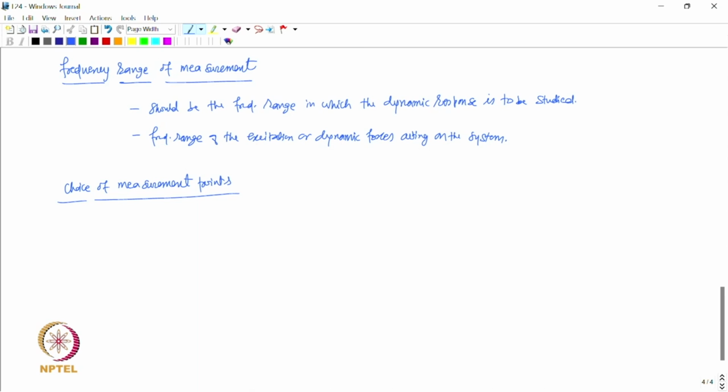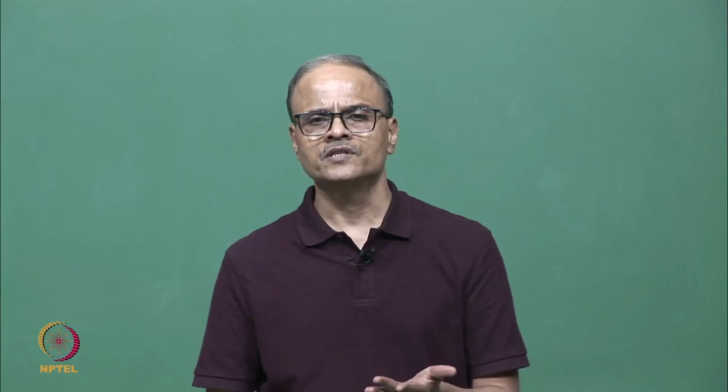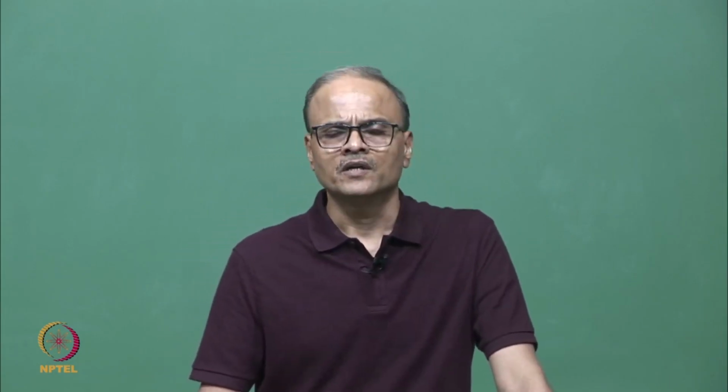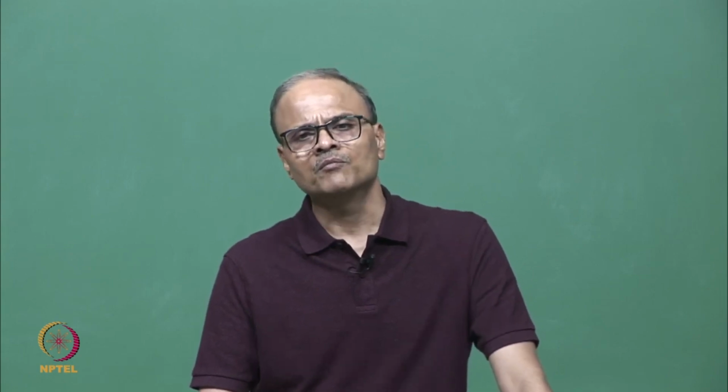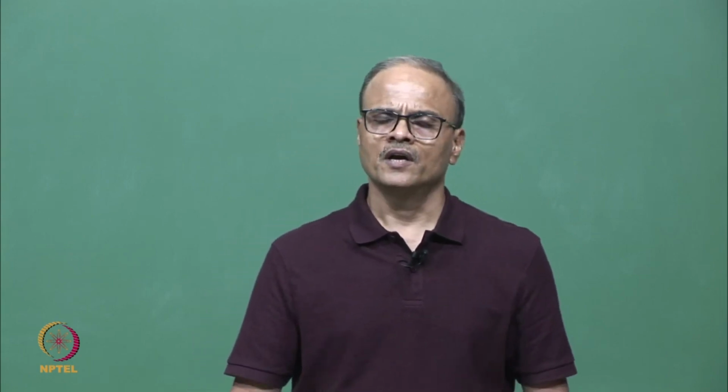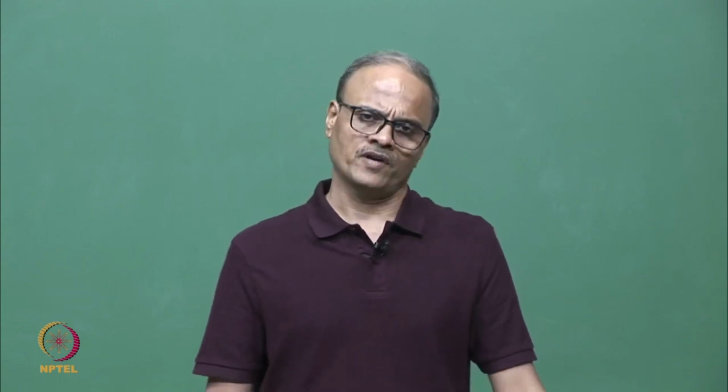If the objective of the modal test is just to determine the natural frequencies and damping factors of various modes, right, then that can be done with a small number of FRFs. So, we can measure FRFs at a few points, and then analysis of that can reveal the information about the natural frequencies and damping factors.